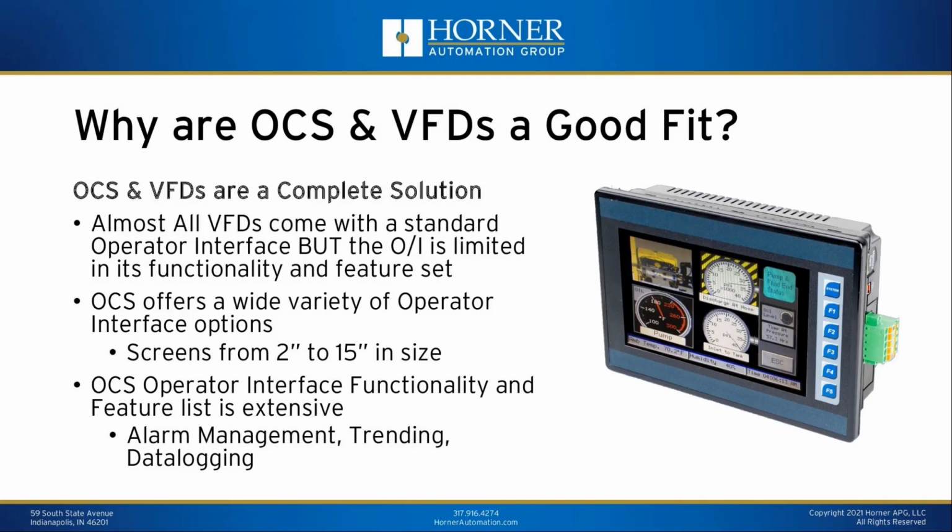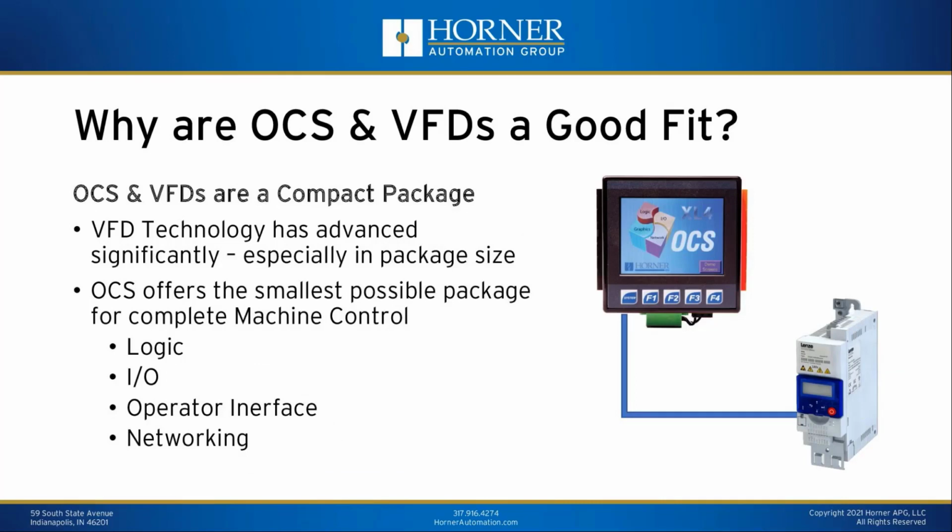You can not just do basic starting and stopping of the motor and controlling speed and parameters, but also coordinate the entire machine and perform advanced functions like alarm management, trending, and data logging. So certainly that is another way that the OCS helps make a VFD a complete solution.